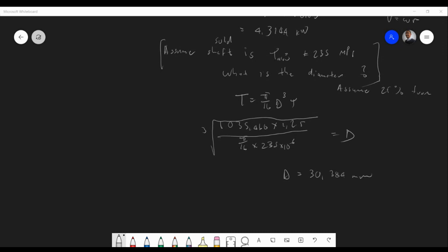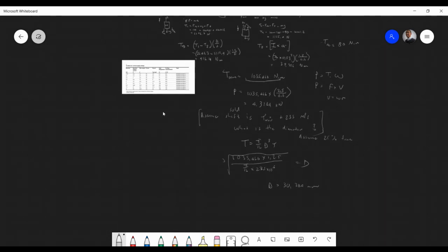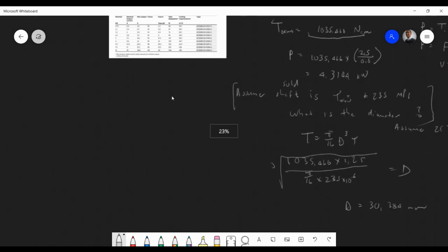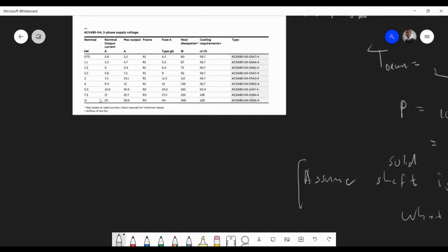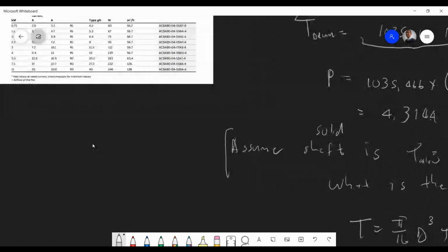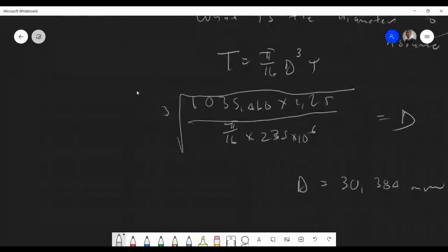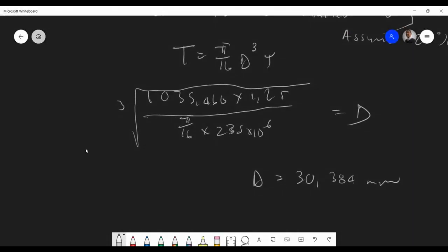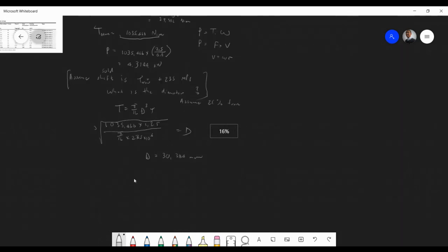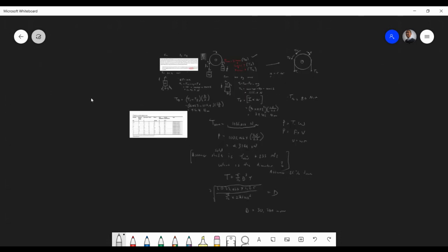So guys, the whole point of this is just showing you a small idea of how I could ask you to determine the size of the motor. Once you find the total torque and get the velocity, you can choose a motor. And also as a bonus question, maybe I would ask the size of the shaft. This is just to make things interesting, right? So anyway, let's move on to the next example. I assume there's no questions, so I can do the next one.